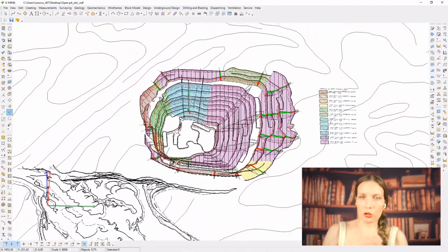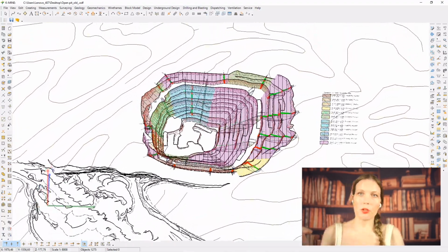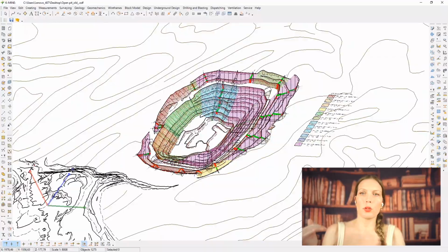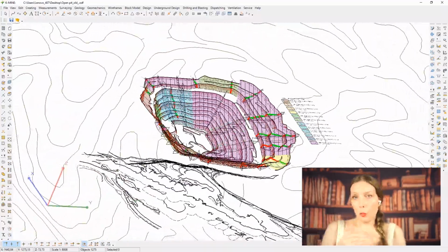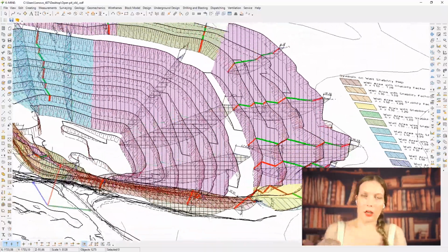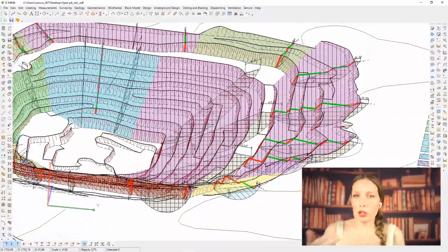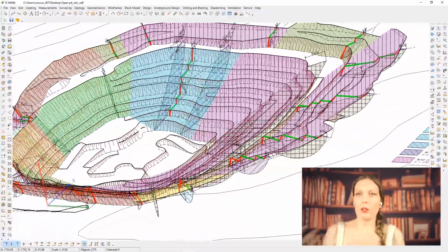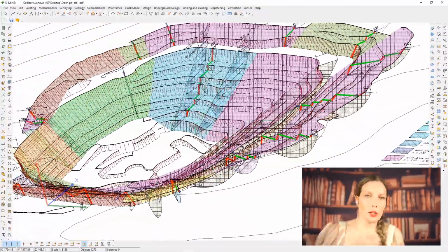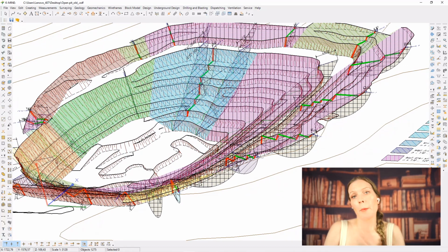But it's important to stress that any calculation result must be interpreted critically. A model is a simplification of reality, even a good model. So, engineering judgment is essential. Comparing different approaches also adds confidence. For example, if both limit equilibrium and FEM produce similar safety factors, the results are likely reliable. But if they differ greatly, something might be wrong.